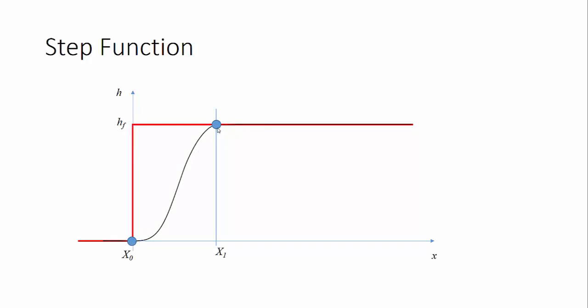So what is a step function? The step function allows you to have a smooth transition between two values. So instead of jumping from 0 to this high value in no time, what we are trying to do is to make this transition smooth like this. When we have this smooth transition, it makes the change in the velocities and the acceleration smooth. The forces will not be as high as they would be when we use this simple case. So how do we do this? There is a mathematical function in Adams that allows us to do this. We call it a step.